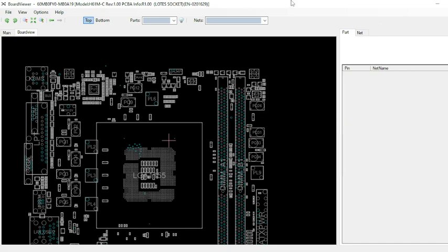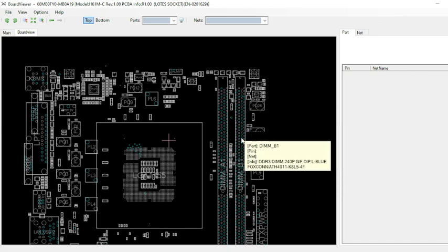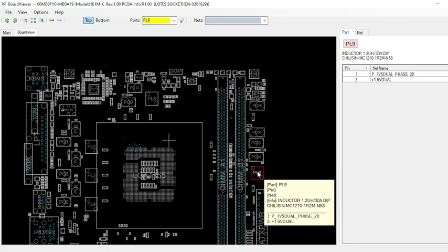First of all, in the RAM section you have to check the RAM voltage, which you can check on the RAM SMD capacitors which are available, or on this coil. It should be 1.5 volt. Next, check RAM VTT, which should be half of the RAM voltage, 0.75 volt. You can check that RAM VTT on pin 120 or pin 240 of the RAM socket.